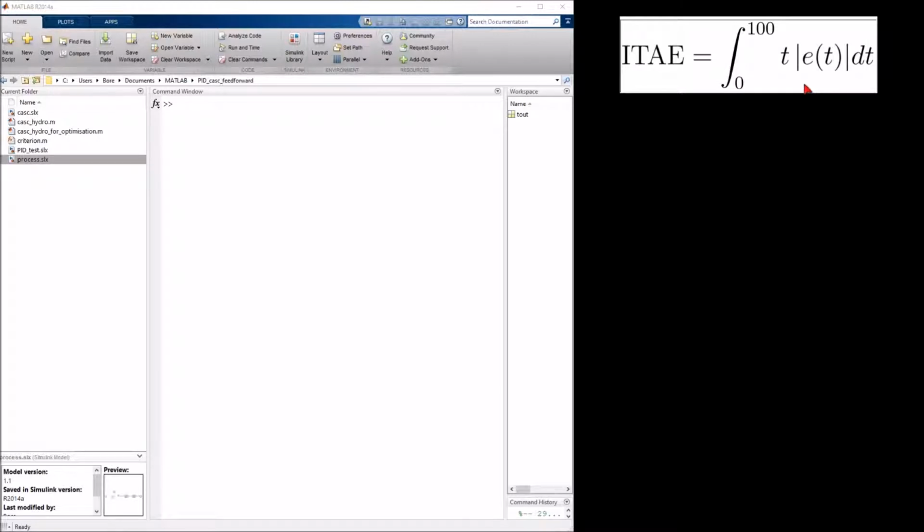For the implementation of the criterion function, we need one integrator. We must generate the independent variable with clock signal. We must use the block which will calculate the absolute value, and then we must use a dot product block to implement this product. And of course, we shall also use a block which will simulate the error signal. Namely, we will use one block from lookup tables library. And of course, we also need some blocks for observation.